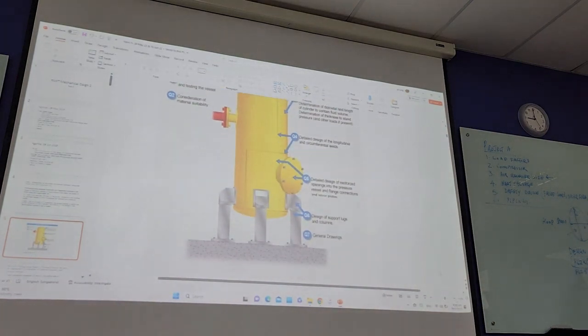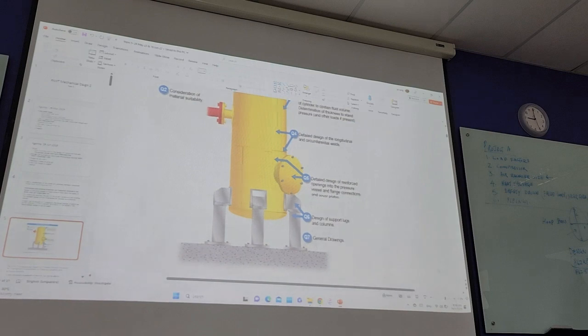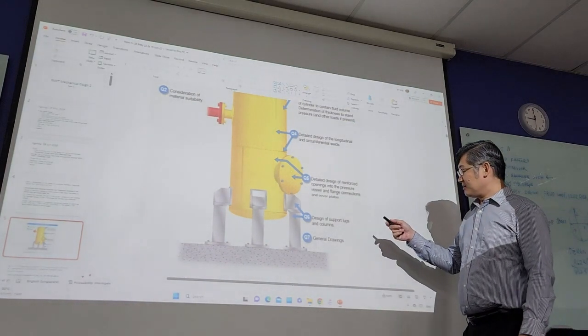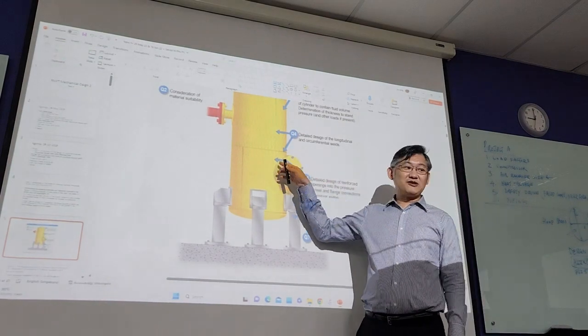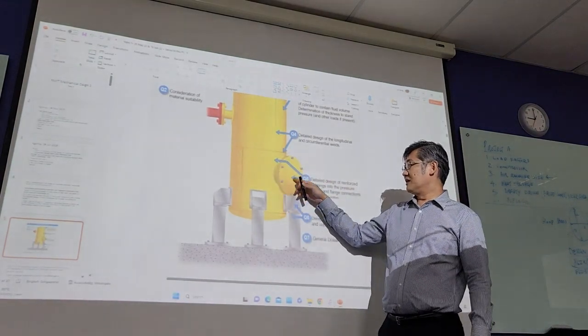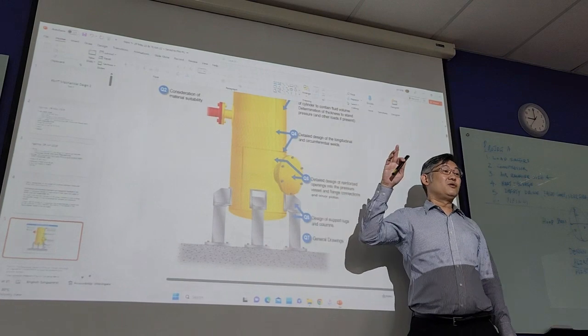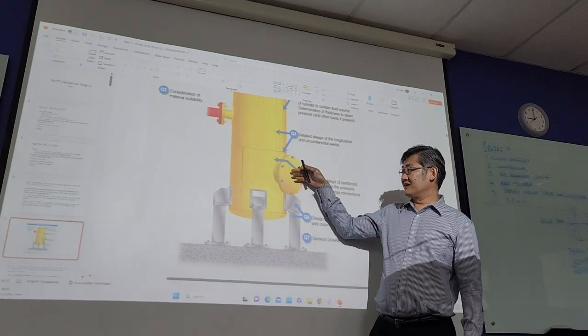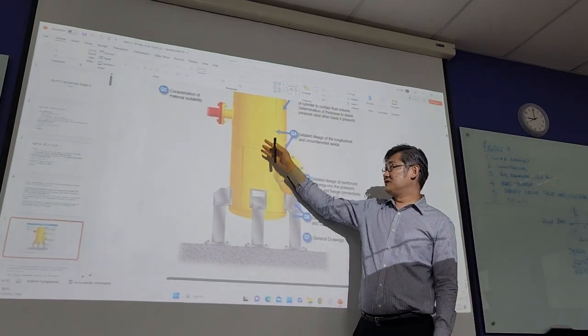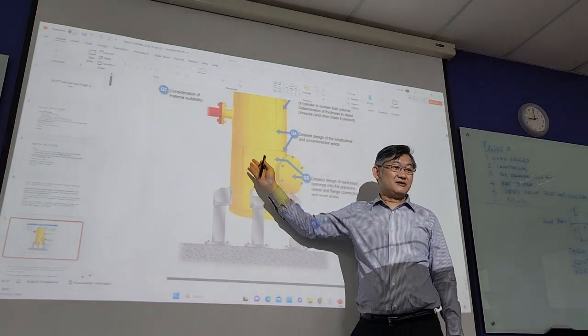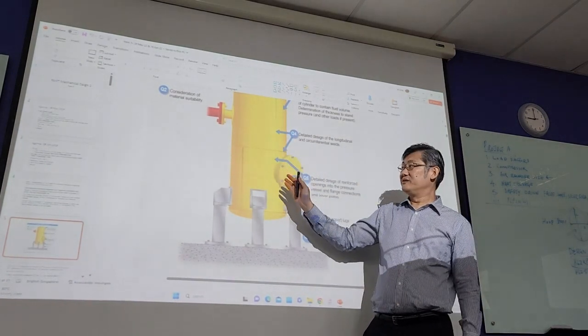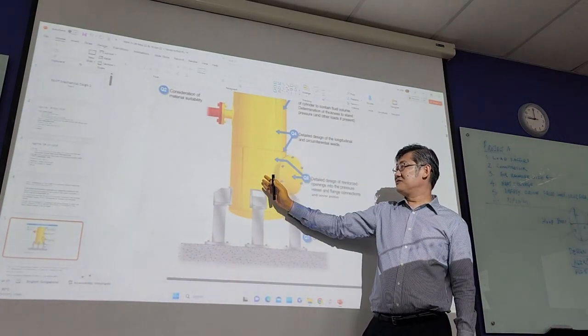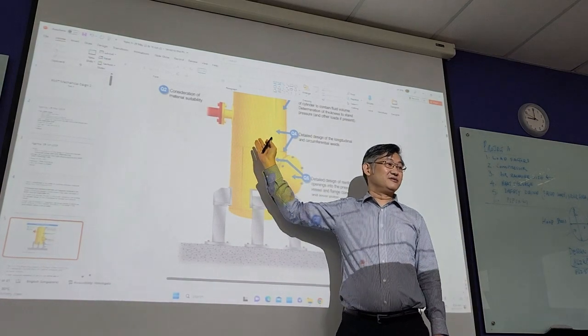Flange connection, you can see. What they want to do is, for inspection purposes, you have to cut a hole, a manhole, so we are able to access. We want to inspect any corrosion inside the vessel. This is a requirement. Because later on you will see, your vessel is about 5 meters.